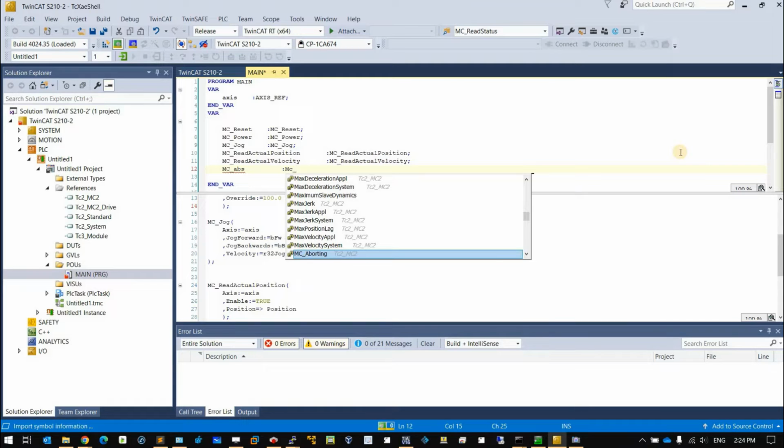And also you can use a minus command set point to let the drive run in the other direction. For example, you pass minus 200 mm to your drive to execute this function. Then after executing the function block, your actual position will be 700 minus 200. It will be 500 mm. Just like this.